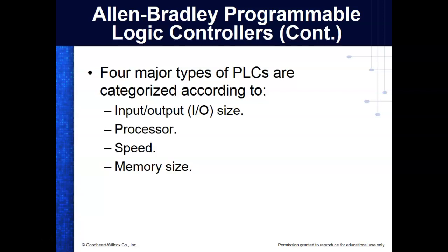Those are probably one of the predominant ones that we have. Very seldom do we see true racks anymore. It'll be a DIN rail that you mount, and then the PLC pops onto it, and your actual backplane runs through the PLC itself. And you need to know the programming application. You don't want to buy 4 or 5 different PLCs because you'd have to have a different application for every one of them.